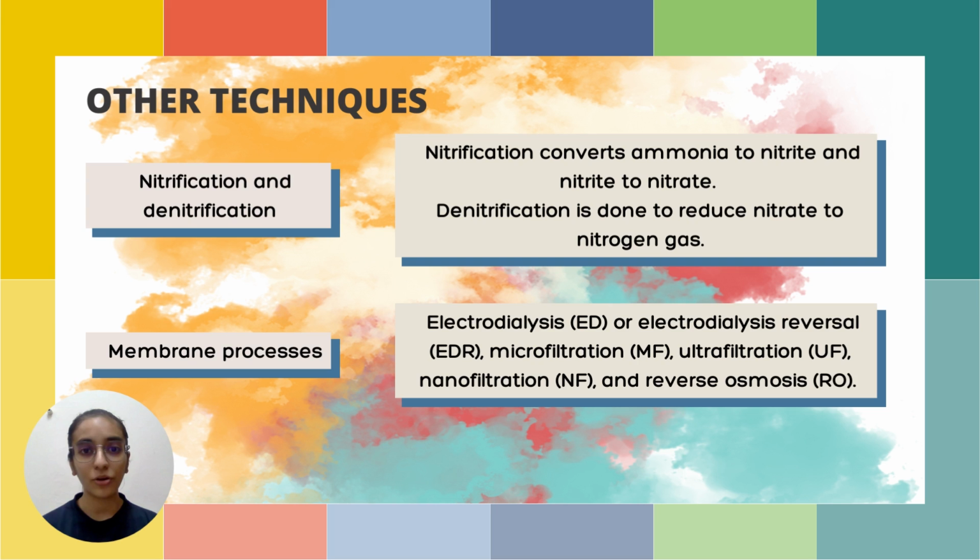Membrane processes are another technique that are essentially advanced filtration processes that utilize the separation properties of finely porous polymeric or inorganic films, and they can be classified into several sub-processes such as electrodialysis, microfiltration, ultrafiltration, nanofiltration, and reverse osmosis. In the case of electrodialysis, the application of an electrical potential will provide the driving force for the separation. Microfiltration, ultrafiltration, and nanofiltration will make use of the size difference between the particles to be separated and the pore size of the membrane.